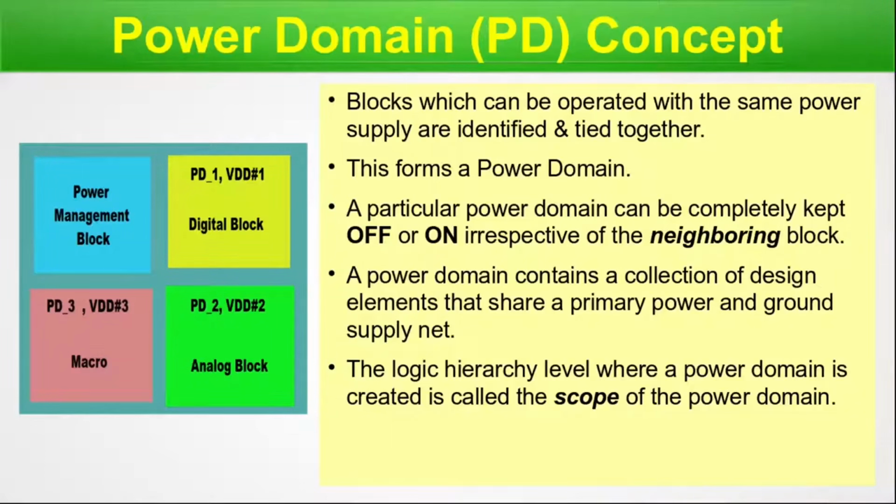Here I have not shown any hierarchical design, but in upcoming slides I will show you the hierarchy, because there could be different hierarchy levels: the top level, 1 level down, 2 levels down, 3 levels down. The level at which the power domain is created is called the scope of that particular power domain.